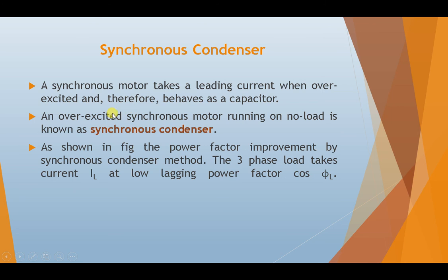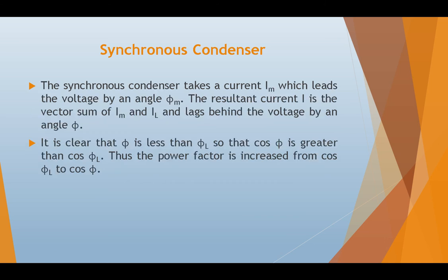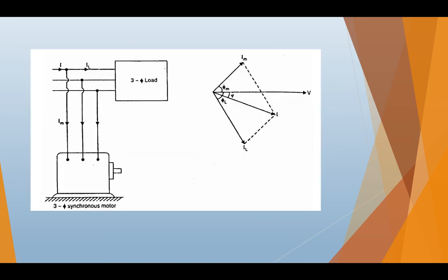An over-excited synchronous motor running on no load is known as a synchronous condenser. For the synchronous condenser, let's see a diagram and figure. This is the three-phase load, and we have a three-phase synchronous motor connected with it.